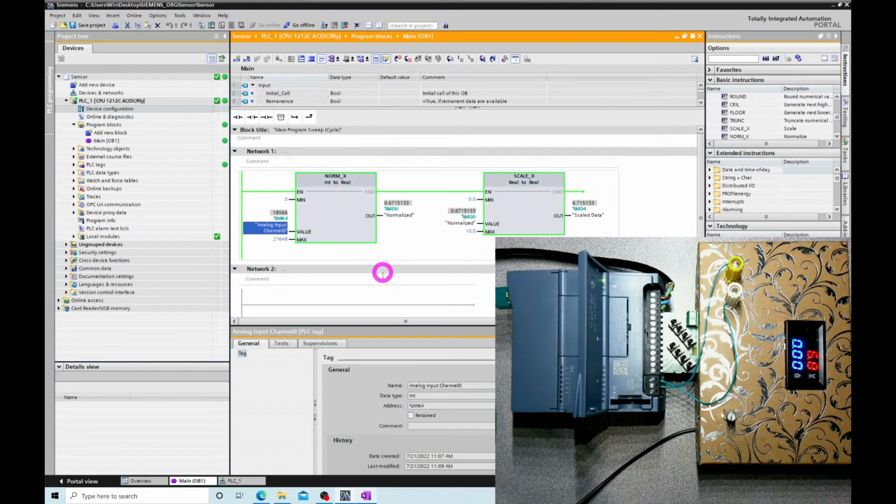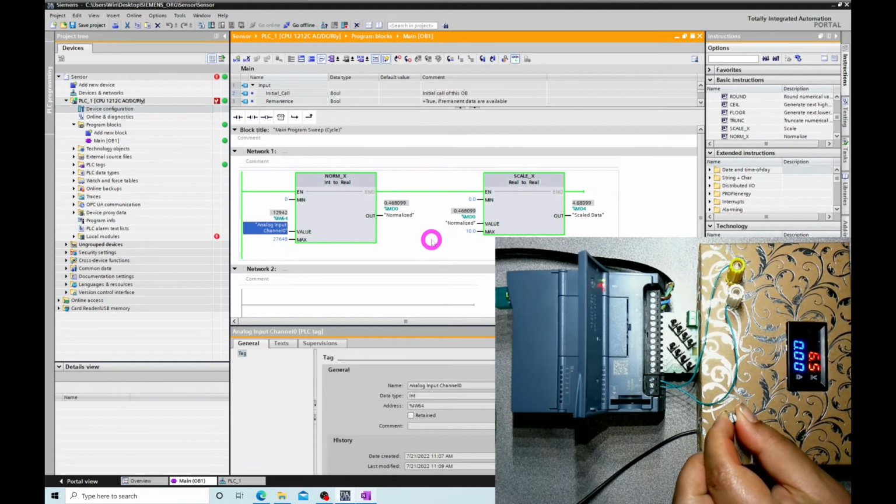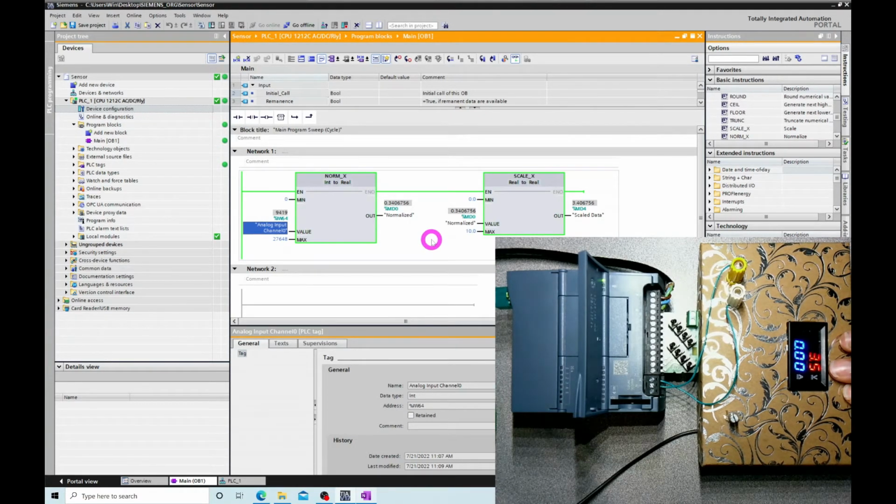Let's just start with a small value. Let me go down to 1, for example. Then go back to the other values. This power supply that I have is not very accurate. We actually made it ourselves in the lab with the students. So it's okay, at least for this application. Now what happens? I put in 3.1, 3.5. That means if this is my sensor, it converts the physical quantity value to 3.5 volts. Then I should be able to see that in my program.